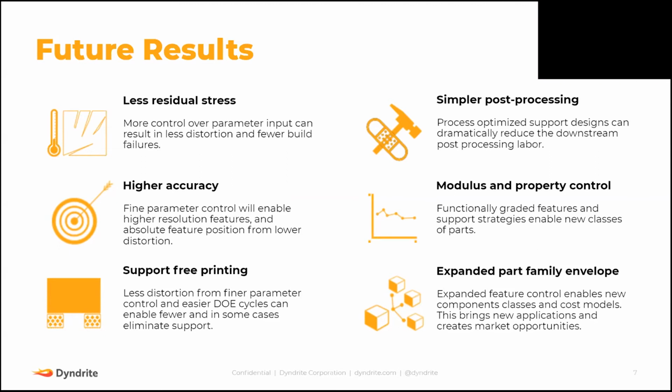Yeah, it's an interesting one. So you could talk about functional grading at a couple of different levels. You could talk about it in terms of microstructure of the metal itself, or you can talk about it in terms of quasi materials. So anything from a lattice shape downward. In terms of functionally graded microstructures, so deliberately perhaps inducing porosity and things like that, substantially less widely used. We do have a number of customers that are doing it for very, very niche applications.